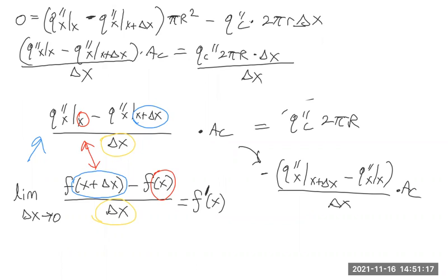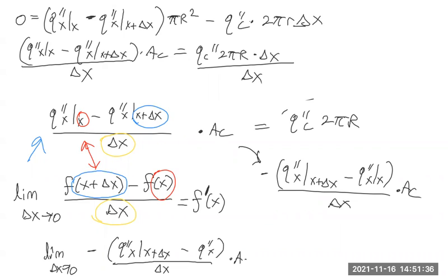So here we can just say, take the limit as delta x approaches 0 of the heat conduction side. And you also have to take the limit on the other side, with the Newton's law of cooling. But the nice thing here is there is nothing that is changing with delta x, so this is just going to be the same thing. What's going to change is the left-hand side. So I'm going to go to the next page and rewrite what we have just written down earlier.